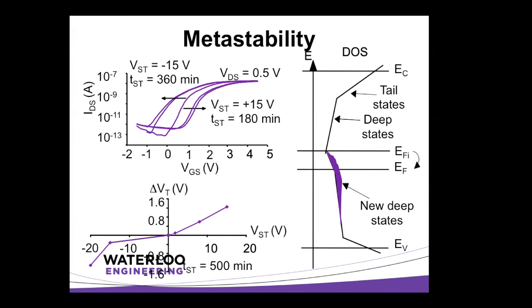That's what it was. Now, the other problem you run into with amorphous materials is, because of that entire defect profile in the semiconductor, you have an issue with traps. You have an issue with deep state traps, which are in the bulk, and you also have an issue with shallow state traps, which are on the tail, or on the edges of the band gap, right? So in this case, for example, here you've got deep state traps, and then you've got some more traps sitting near the conduction and valence band edges.